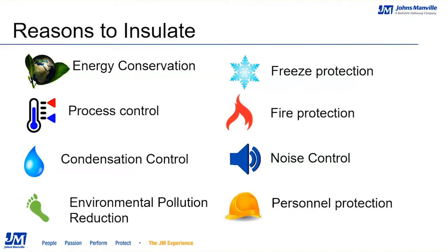Another reason to insulate is to control condensation. If not controlled, condensation can allow mold and bacteria growth. Condensation can damage building materials such as ceiling tiles. Condensation can also cause potential safety issues such as slips or falls from pooling water.